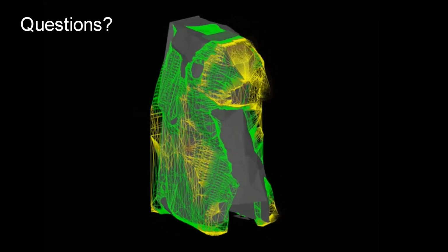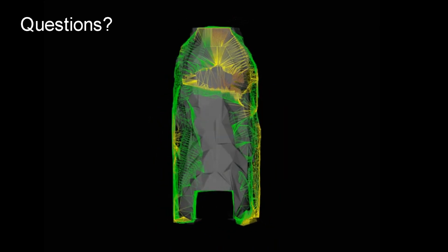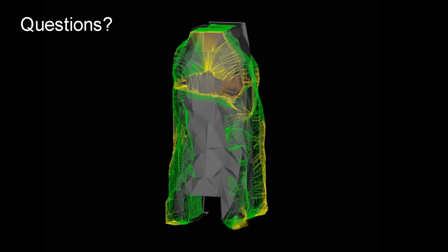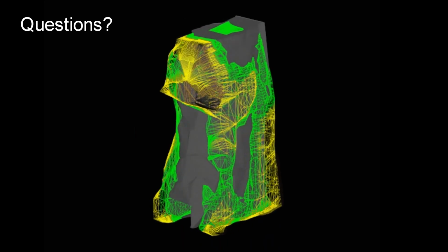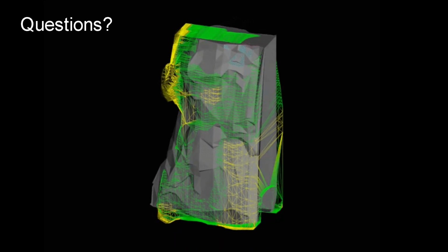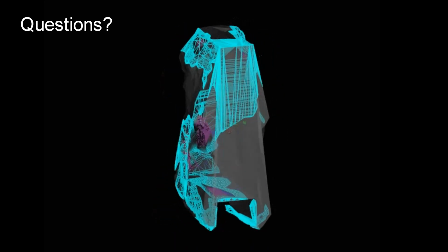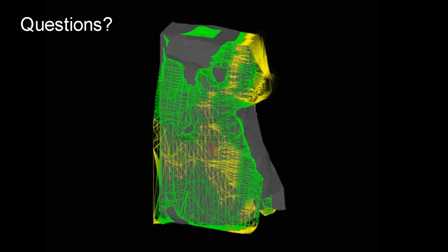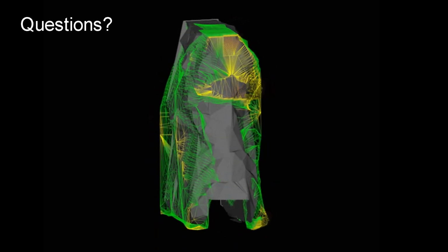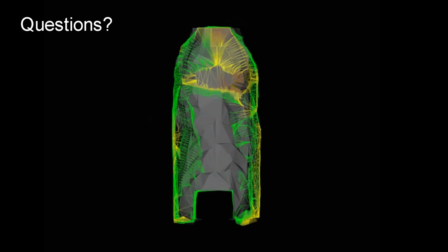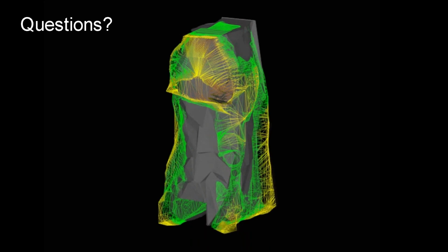And also, if we're rushing our drilling, we'll tend to find deviation in the drill holes, especially with a long hole stope, there's a lot more opportunity to deviate. So there's definitely a balance with how quickly we need to go to maintain profitability, but also understanding that if we rush it too much, we can deviate beyond the design, which, as shown here, can be quite costly as well.